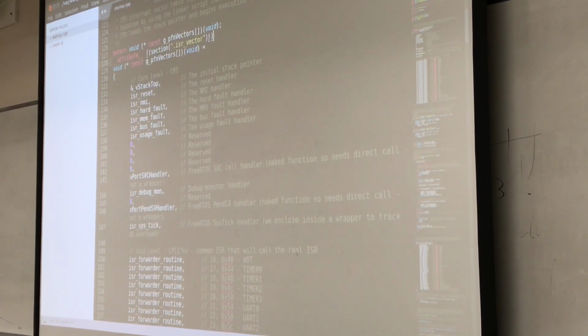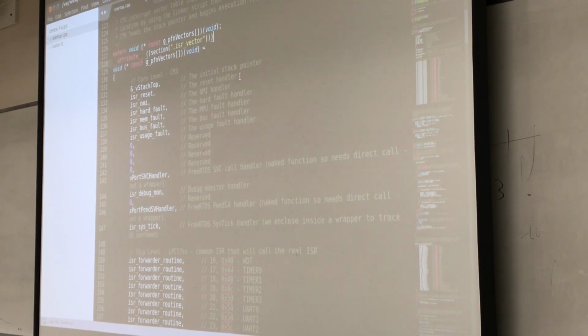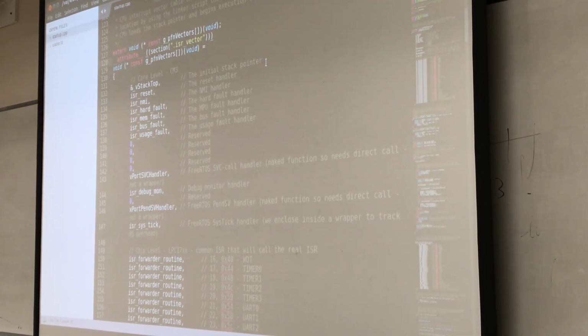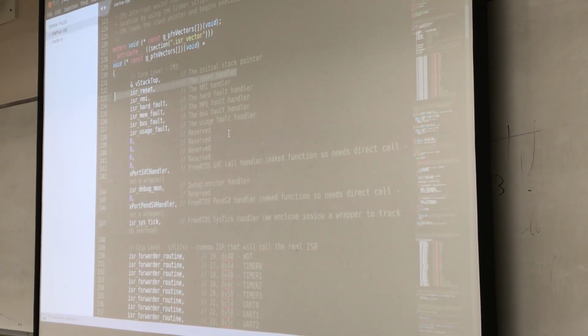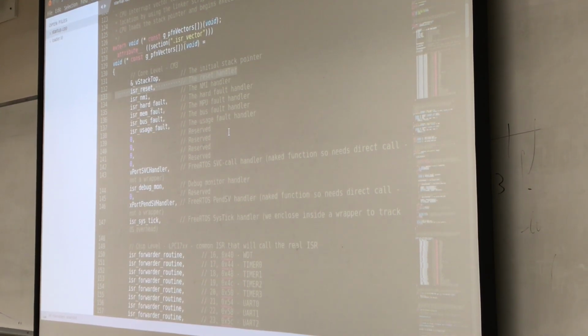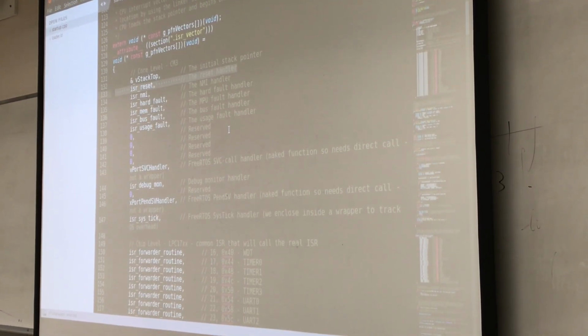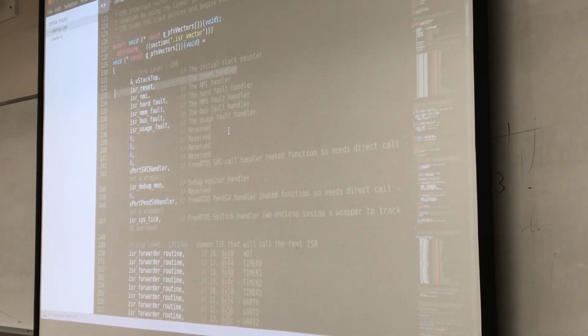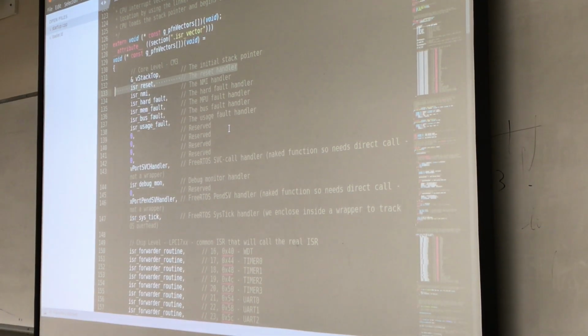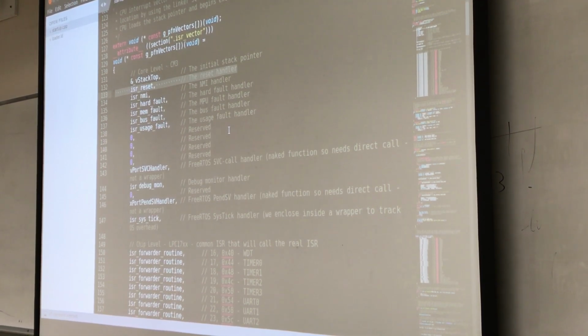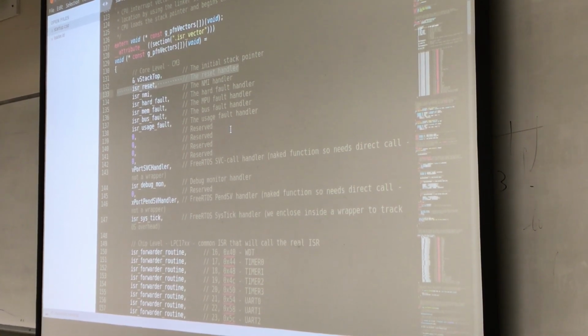The first interrupt you can see in line 133 is the ISR reset, which is a non-maskable interrupt with the highest priority. No matter which interrupt you are currently executing, when you get a reset interrupt, it holds the highest priority, and it is going to reset your microcontroller by addressing this interrupt. Each of the interrupts here would have an address that it refers to, which has the ISR routine.